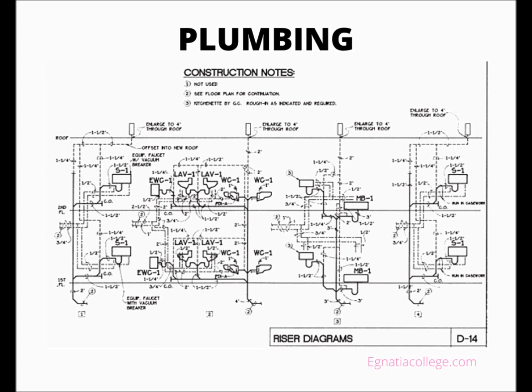A plumbing riser diagram is only used to indicate design intent and does not indicate a piping route. The sizes indicated by the engineer are minimum sizes. Company preferences and local codes can dictate that larger sizes be used.